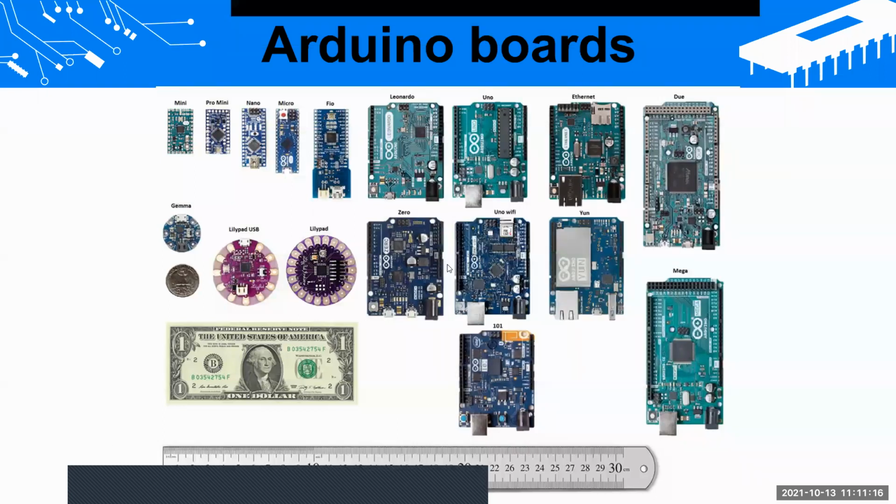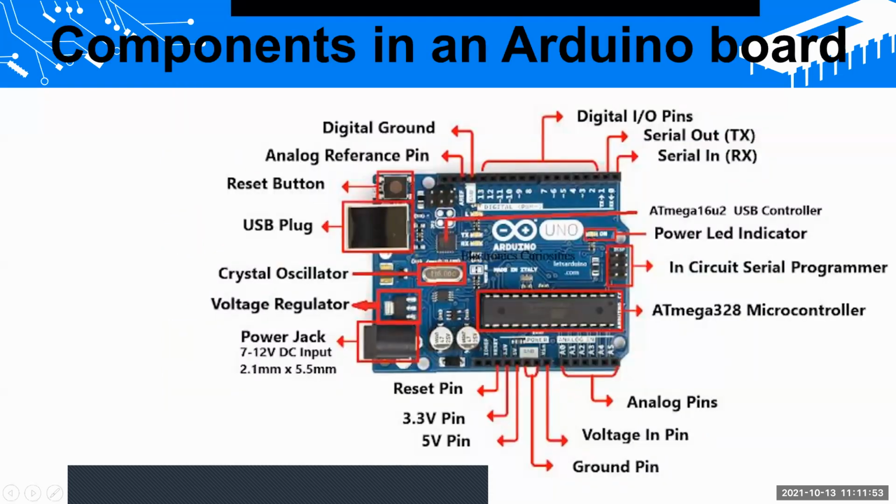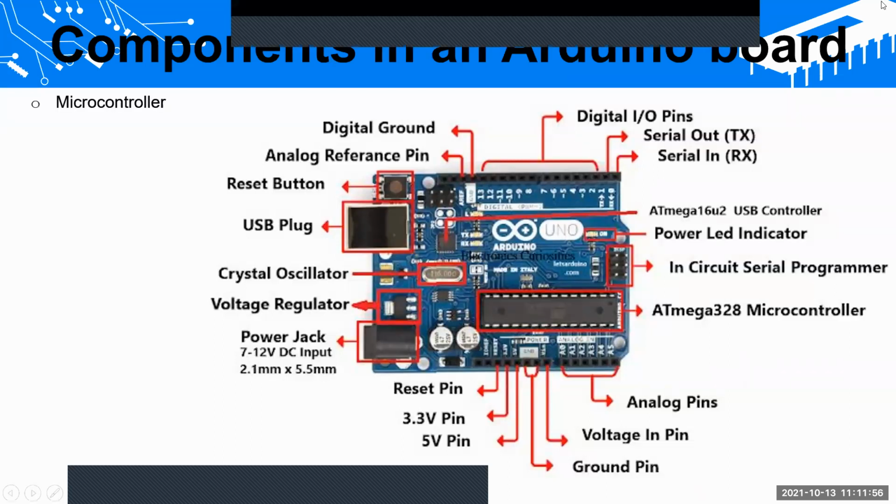Normally we go for a basic Arduino board. Then if you need certain functionality, like Wi-Fi or Ethernet, or GSM modules, like if you need to track the GPS location or send SMS messages, for those things you can use GSM shields. So we start with the very basic Arduino board, then we stack up the shields we need. That's how we are going to do it.